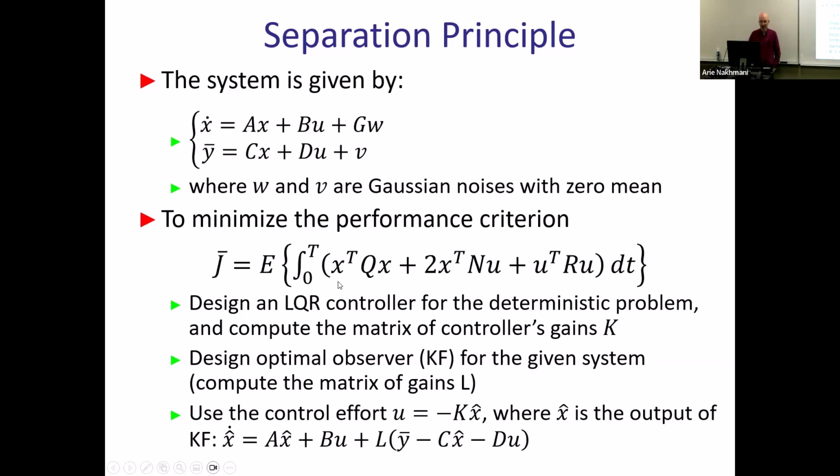We saw multiple other things. You can add an exponential part here. Remember, you want settling time to be faster than some particular number. So you can add the exponent and other things that you are used to. The point is that it doesn't matter what kind of criteria you're using, just use that criteria and compute your LQR completely separately from Kalman and design that controller, and you will get the controller gain K. So you'll have that vector.